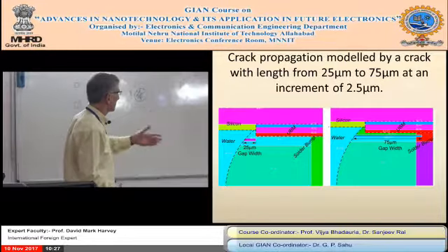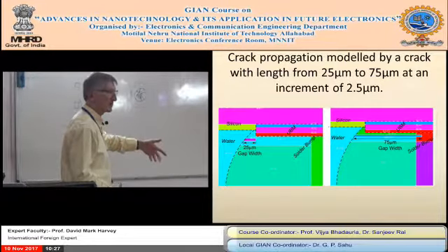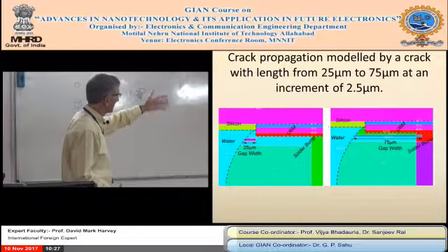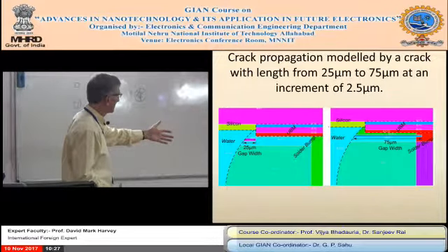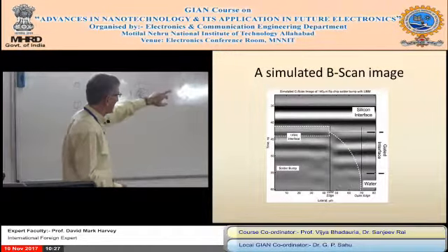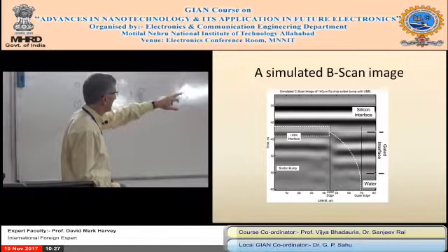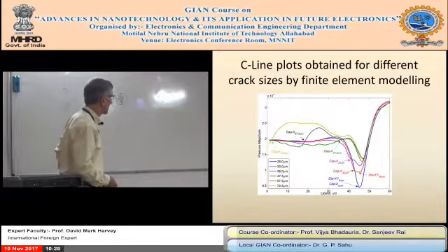So then from his results he gets this automated or simulated B-scan now, similar to what we get from a machine. And you can see it looks similar to the initial real one. But what I discovered was the dip, due to the edge effect, you can find from that trace by gating out the B-scan between, in this case, 43 to 55 nanoseconds. You can try and find out, and he calls that cap X.